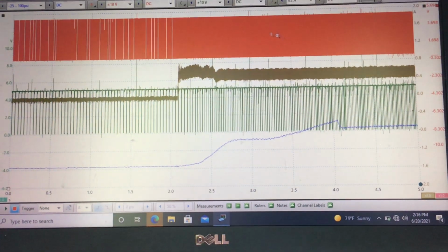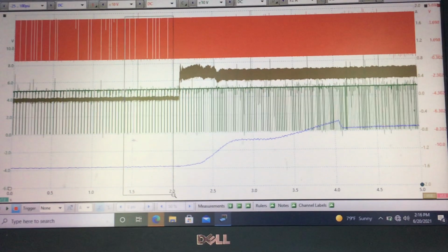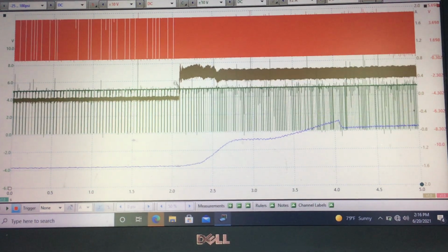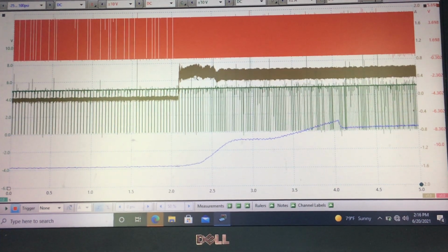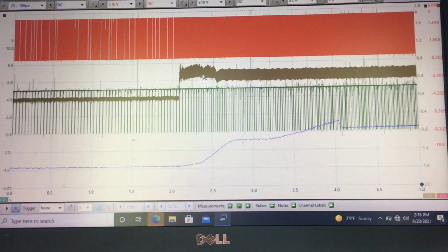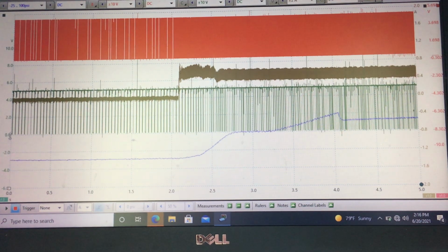Red is the crank sensor. Green is the intake cam sensor. Yellow is the current going to the phaser, going to the VTC solenoid. The solenoid duty cycles and sends a certain amount of oil pressure up to the chamber in the actuator by the cam sprocket to phase the intake cam. Channel A is the WPS 500, which is where the oil sender came out. That is actual oil pressure. Let's take a first look at our first capture.